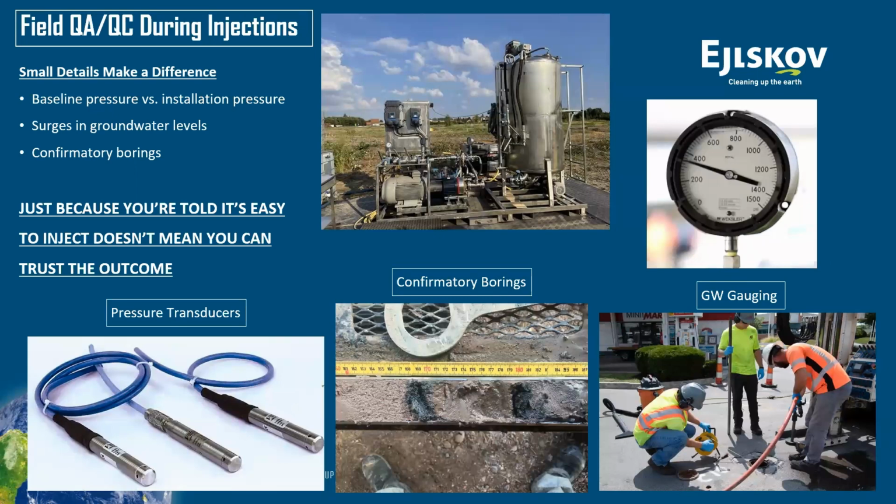Am I getting good distribution? Is there something that I'm not able to obtain down at the nozzle with my equipment? Am I capable or not of pushing the material where I want to? And when I work in sands, if I see, for example, a pressure constantly rising during the injection period, that would also sort of raise an alarm.